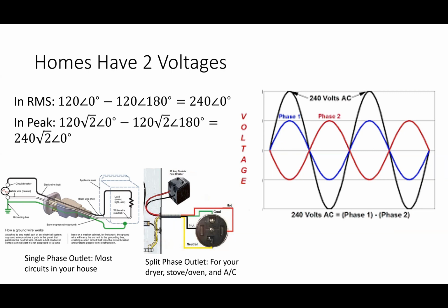Yeah, it's work over time. It's the rate at which energy is being used. If you've ever looked at an electric bill at home, you get charged for energy. When you look at a commercial or industrial bill, you get charged for two things: demand and consumption. Demand and power, we use those terms interchangeably. Demand is the rate that you're using energy, and energy is what you consume over time.